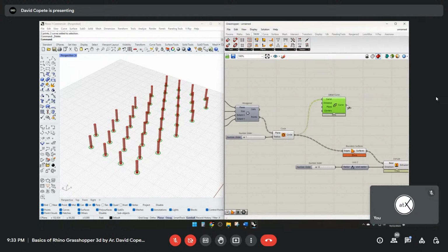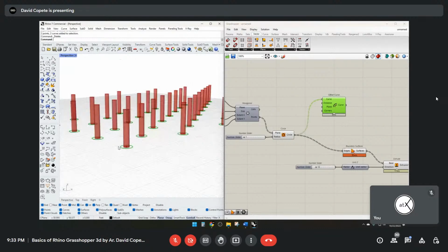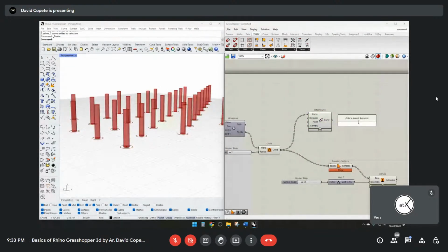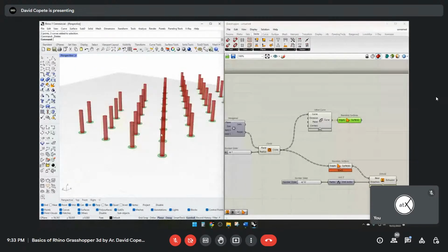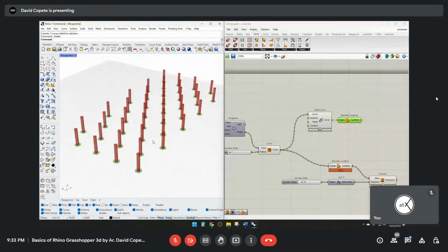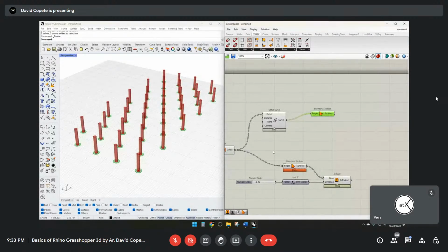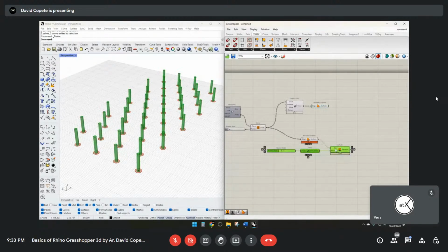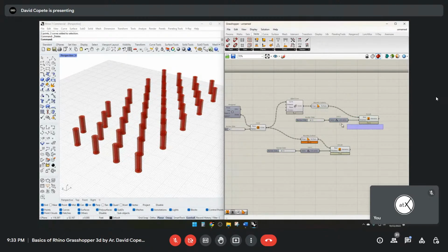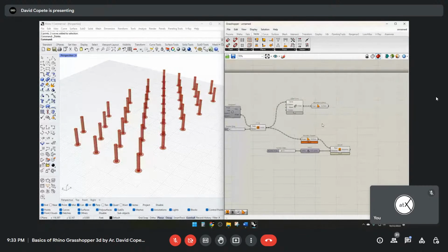So with this, we'll create another boundary surface. Let's go here to boundary surface, which will create a surface inside of that offset. With this, we're now going to extrude it the same way that we did this here. Now, I can technically take this and copy it and plug it in. So this is sometimes the workflow that I use, but I'm trying to go slow and kind of be careful with this with you guys.